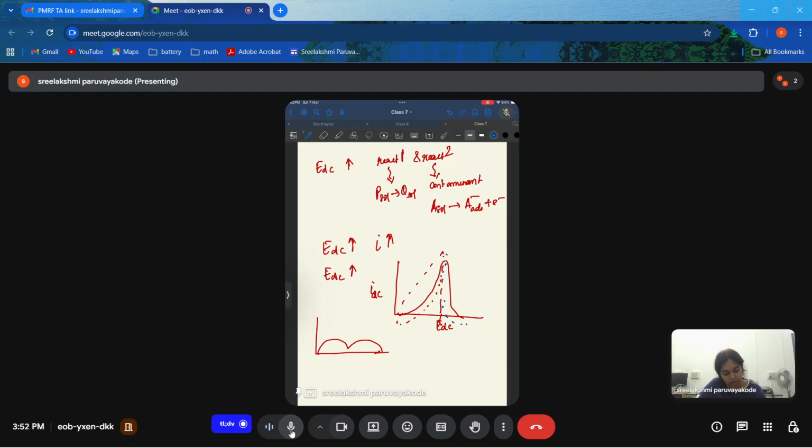So when we are going for the case where the DC potential is such that the current reduces with the DC potential, at any of these points, if we do the impedance, we'll get a negative impedance. Why? Because the differential impedance is considered and that is negative. We'll get something like this. This is for a particular value for this system, but the graph can be anything. When you are doing it for the points where the current is reducing with the potential, you will get a negative impedance, right?